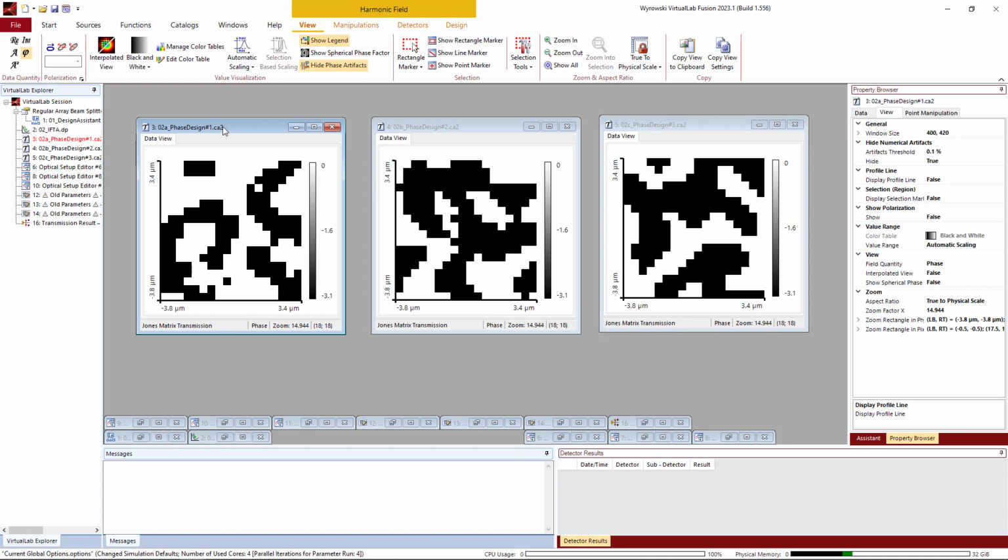And one example of what I mentioned just previously, the fact that here we have a very small feature in this first design, and the trained eye of the optical designer might say, I would prefer not to use this result because I know that smaller features are harder or more costly to fabricate. So as a result of those multiple runs, you are presented with a choice of different designs, and you can use your experience to choose between them or select a few and perform further analysis, which is what we're going to do in this case.